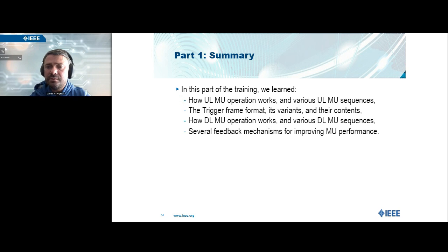I'm not very familiar with the Starlink user ground antenna, but essentially what it does is it allows the beamformer to obtain the feedback from the recipients and then use specific orientations of the beams that you're sending to the recipient to maximize the RSSI at the recipient, so that the signals from multiple antennas can create a constructive wave at the recipient as opposed to a destructive wave. So a pretty straightforward multi-input, multi-output operation.